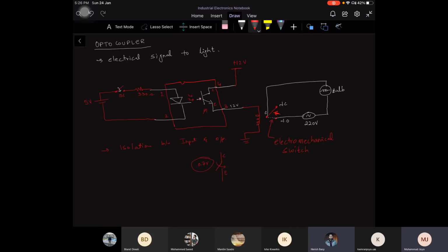Or we cannot use it at all. You can use it. What happens is that when you start switching at high frequencies, the relay will get stuck to one of the terminals. It cannot go back until you disconnect it. This is what will happen. Yeah, because I've used it. I faced something like that. There was a sound in the relay and it was quite stuck, something like that.